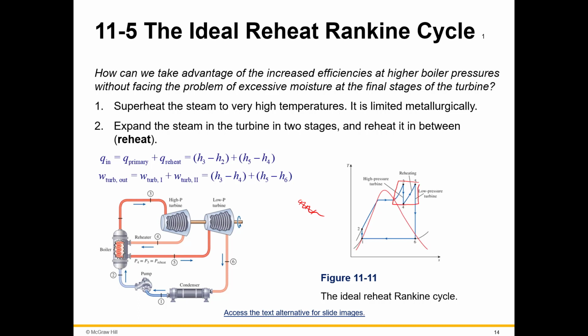right? So we're going up, we have a high pressure turbine, and then we're going to reheat it again so that instead of just coming down here, we get it out from this 2-phase mixture. So we need to move it over. So we're going to reheat it to bring it back up so that it can fall here and have just a little bit catching in this mixture instead of all of this. Right, so that's what we would gain there.